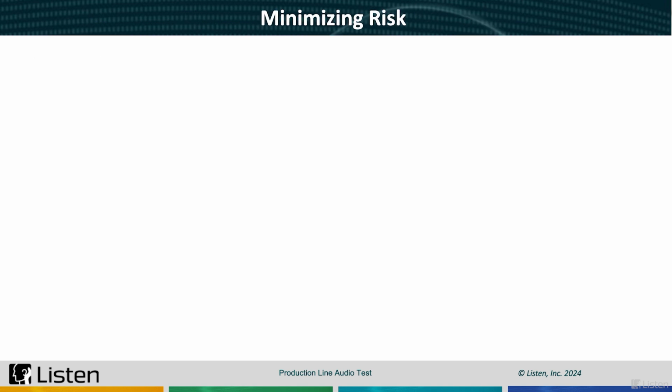Tight control of your test process can mitigate a lot of these problems. The first place to start is your test specifications. The more tightly you specify your tests, the more consistent and better quality your end product will be. Since manufacturers are focused on yield and profitability, they have little to gain by testing more thoroughly than the terms of your contract dictates, so the burden is on you to be specific.